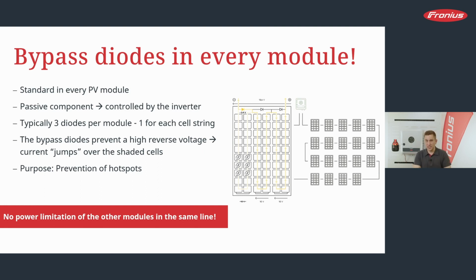The bypass diode, depending on the voltage of the area, will then get active to make sure that the current overjumps this area and is being bypassed by the bypass diode. With that, you have peace of mind that no matter the shaded situation, you have the possibility to overcome this shadow, and to make sure that the rest of your modules, and even the rest of the shaded module, the remaining areas, are performing at good peak performance.